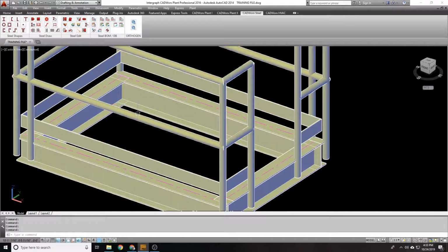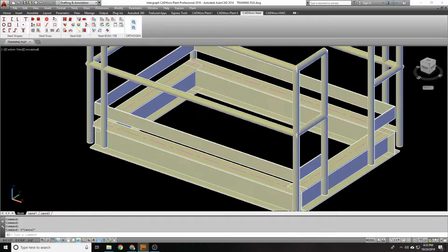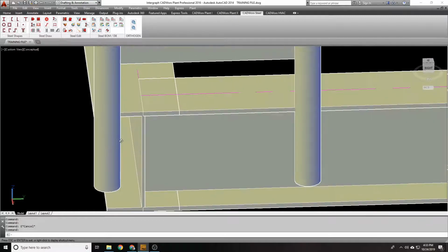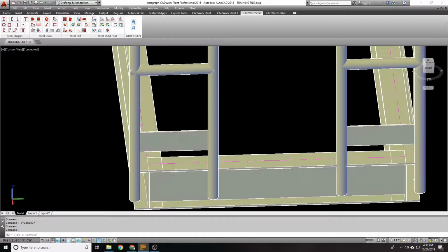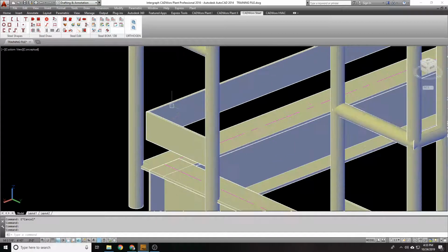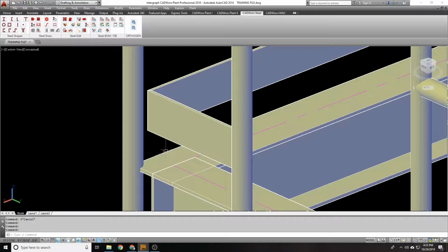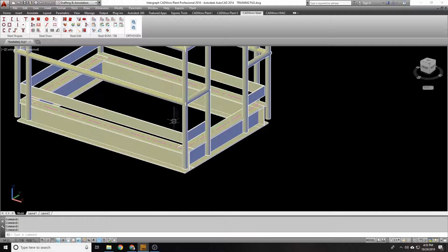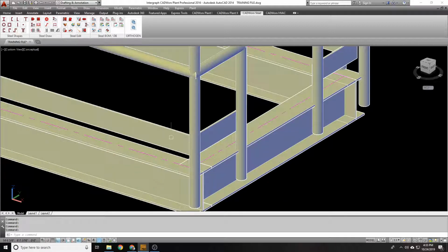Because what's happening is I have not given an offset to the entire handrail. That offset needs to be, well, whatever I need it to be. So whatever the clearance is. So if I want to have like my toe plate to be lined up with the edge, it's going to be that 1 1/16. Or if I don't need it lined up with the edge, it'll be minus 15/16.